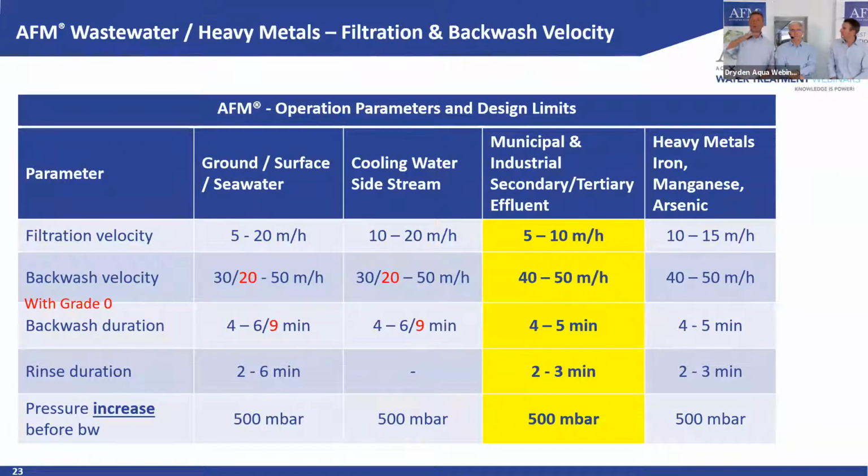That's 1 meter per minute. If you have a 2 meter filter from the nozzle plate to the top diffusers, the water needs 2 minutes to go through, plus 50% safety margin, 3 minutes. If you have 30 meters per hour, you need 2 minutes for 1 meter, so 4 minutes for 2 meters, plus 50%, 6 minutes. And this is where these numbers come from.